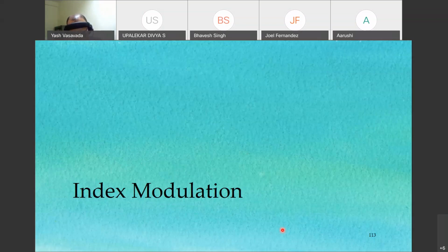The main fundamental task was that we had a set of symbols. For BPSK, it was just 2 symbols. For QPSK 4, for 8PSK 8 symbols, and so on. And we were using some number of bits to select one of those symbols. So for BPSK, we needed just 1 bit. For QPSK 2 bits. For 8PSK, we needed 3 bits.